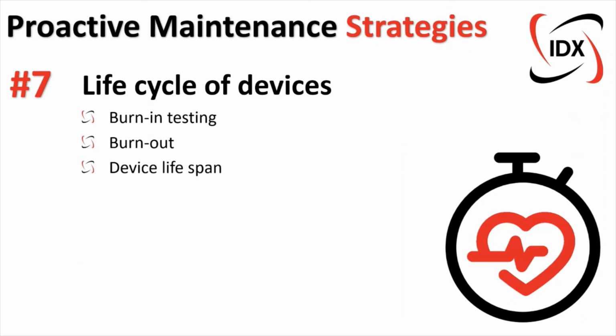And I think it's a very good consideration to firstly make sure you keep spares in stock for devices that are older. Look to do upgrades once networks start becoming a little bit older. And also keep in mind that when you have an older network that's 15 to 20 years old, when you have breakdowns and you're doing an audit, take into consideration that a device failure might be the cause of the error.